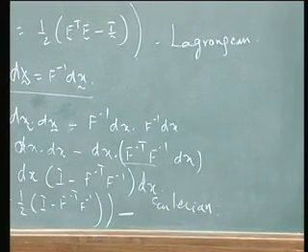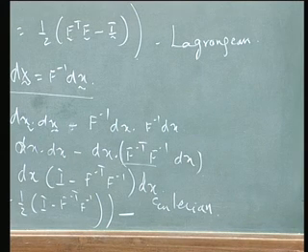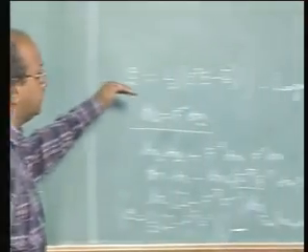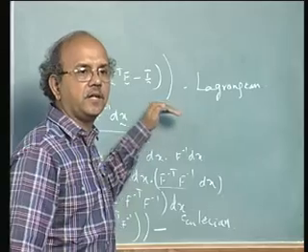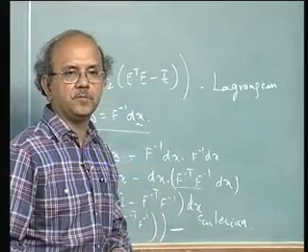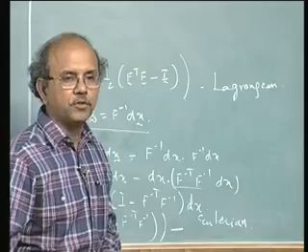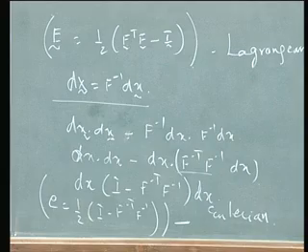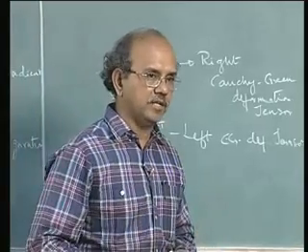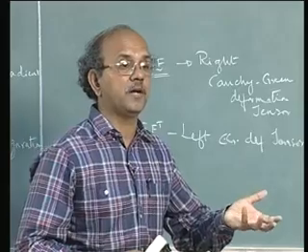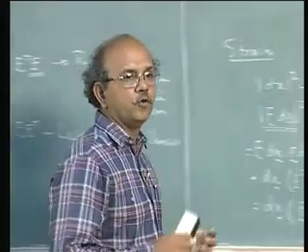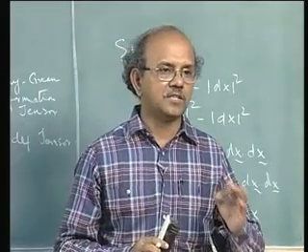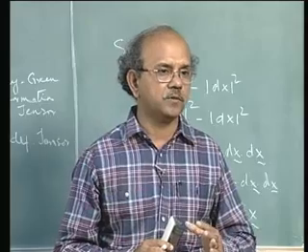So the first thing we have done is to define strains. In order to see what is the connection between the large, this we would call as finite deformation strain or large strain, compare this with infinitesimal strain. In order to do that, let us introduce what we call as a displacement vector and talk in terms of displacements and its gradients, so that we can compare, because we know epsilon ij to be half of dou ui by dou xj plus dou uj by dou xi. So in order to compare both, let us now introduce the term called displacement.